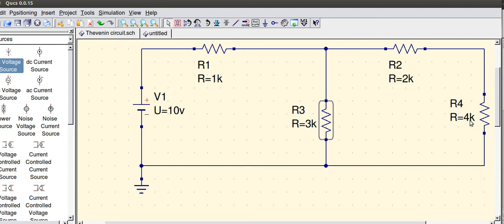When you're doing Thevenin analysis, you can study any resistor in the circuit. However, voltage sources, by definition in the real world, have series resistance, or internal resistance with them. So for the purposes of Thevenin, I'm never going to ask you to study the resistance that is in series with a voltage source, particularly if there's only one voltage source in the circuit. If there's two, then it's possible. If there's only one, then basically the method fails.